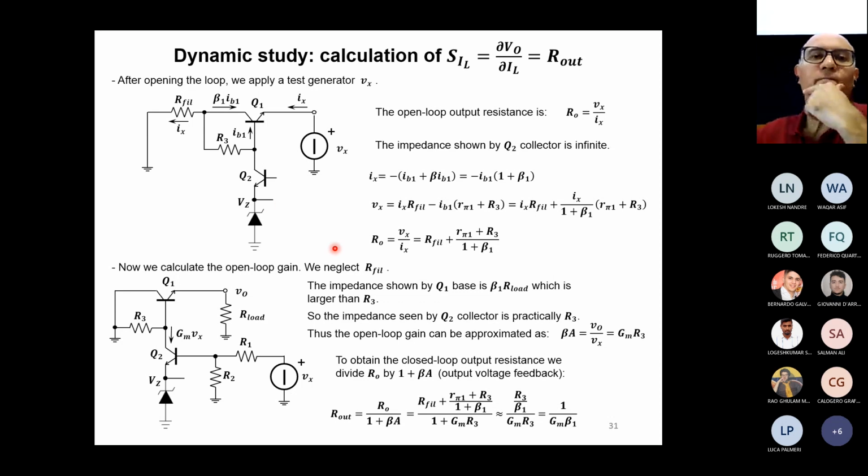And basically, once that we open the circuit, we cut the resistance, we are not sending any signal to the base of transistor Q2. Dynamical signal. There will be a bias, a static polarization, but there is no dynamic signal that is going to transistor Q2. So if there is no dynamic signal going into transistor Q2, I can imagine that basically there is no signal in the collector.